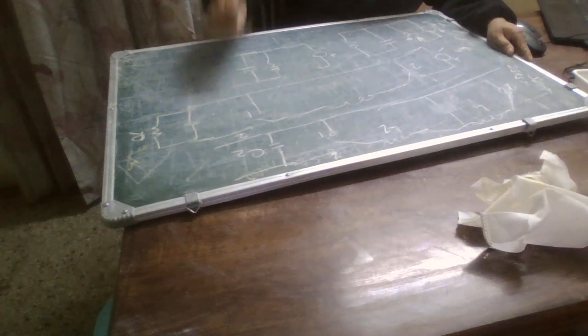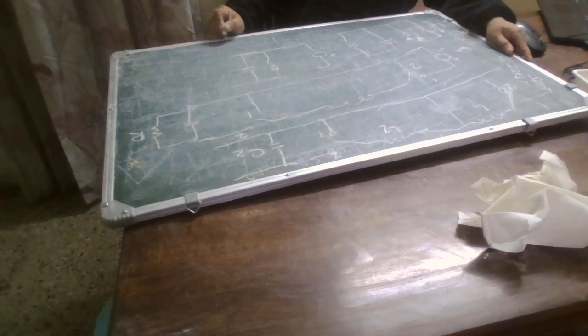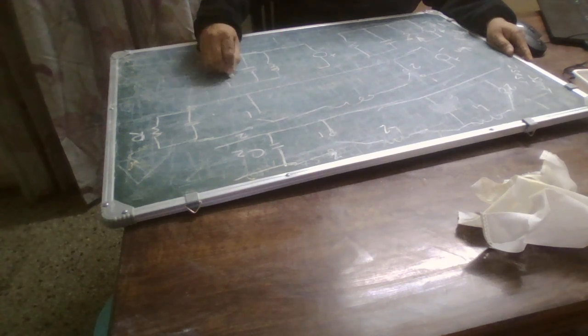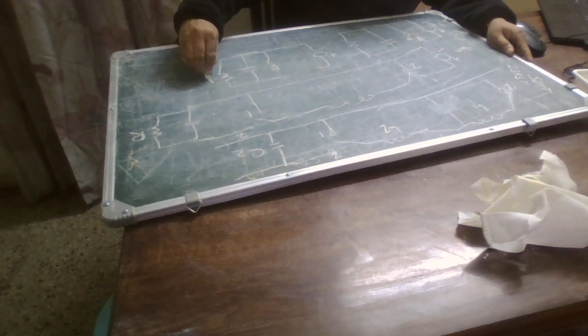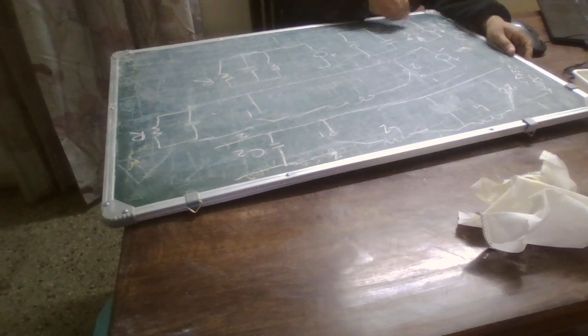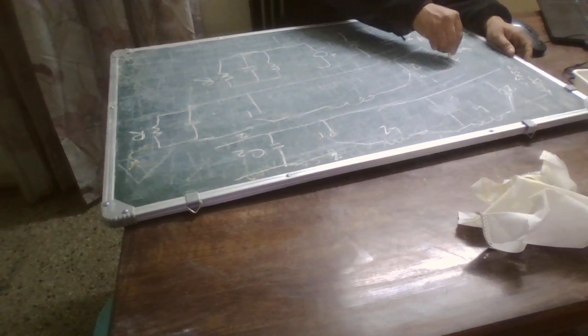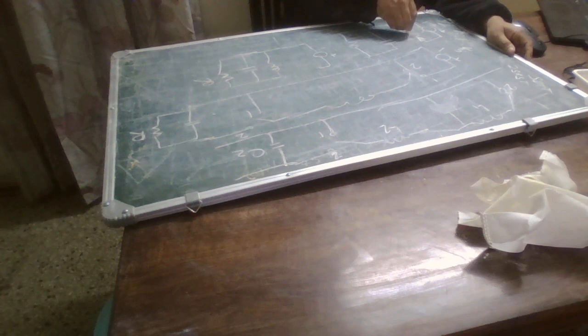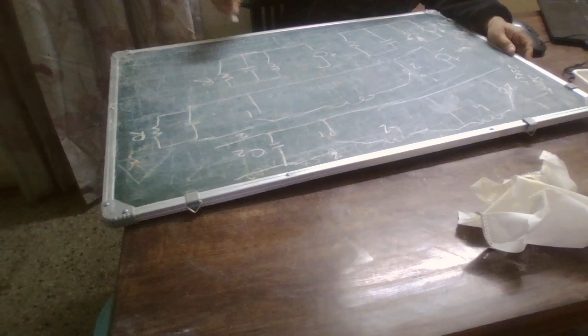Okay, now the inductor is connected to the load, earlier it was connected to the source, and here we are having an output. So we have got that the energy is transferred in this position 1 from the input source to the inductor. And here the inductor is connected to the load, and energy is transferred from the inductor to the load.